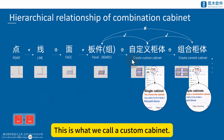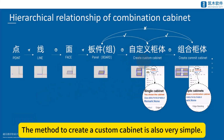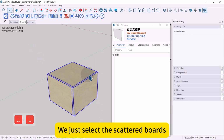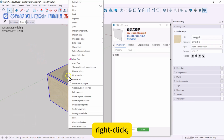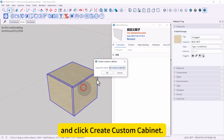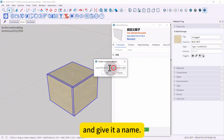This is what we call a custom cabinet. The method to create a custom cabinet is also very simple. We just select the scattered boards, right-click, and in the context menu that pops up, click Create Custom Cabinet. Then we can give it a name. After naming it, click OK.